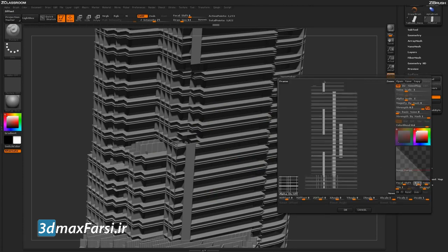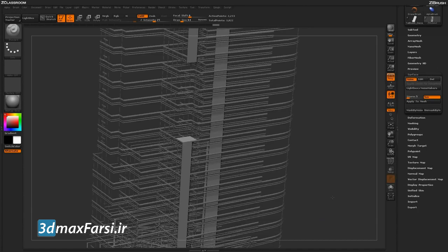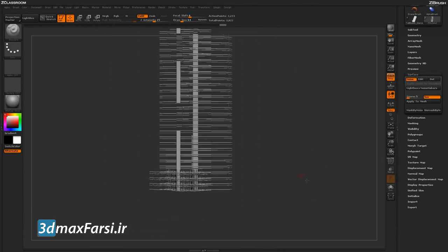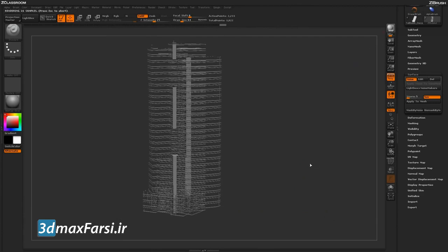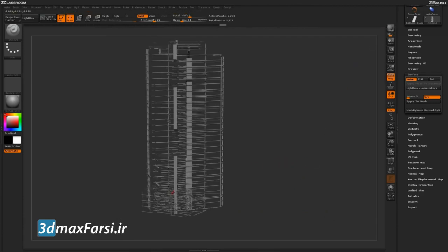So now I can go back into the surface noise modifier here and just click edit, and I'm just going to adjust my offset back to say -0.5, and then I'm just going to hit OK. And now I'm going to render with BPR one more time here. And so now I'm getting this kind of effect. So this is giving me a little more interesting shape, and it's not generating all those rounded angles all over my model where I may not have really wanted them.